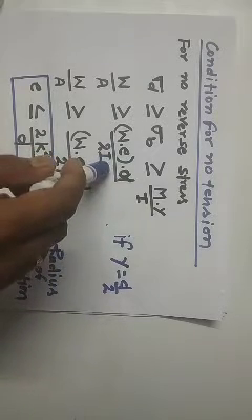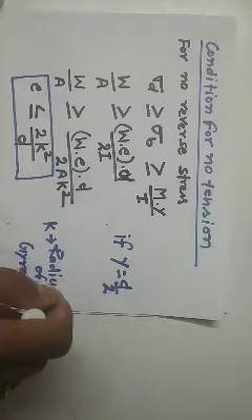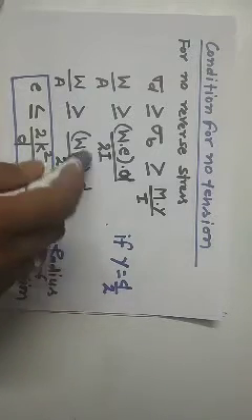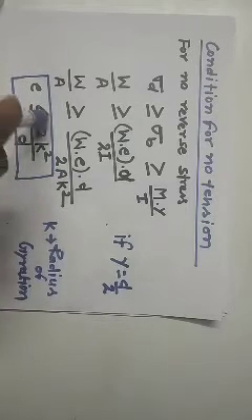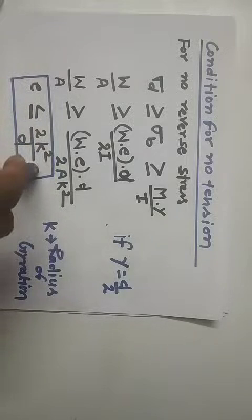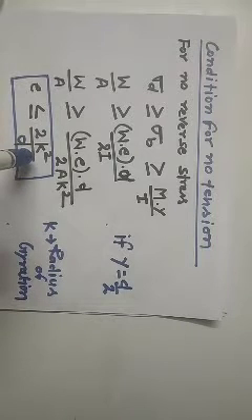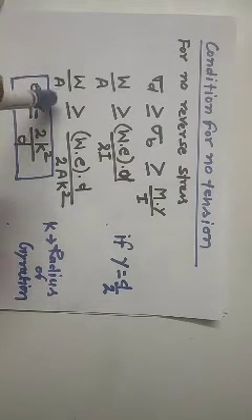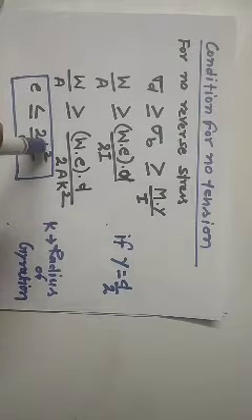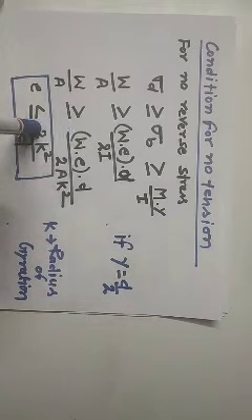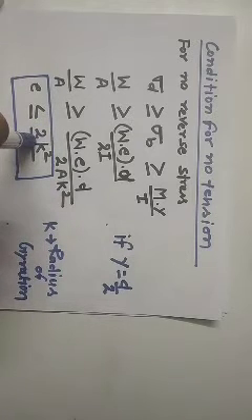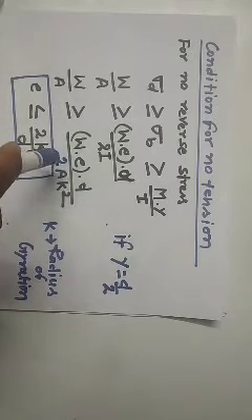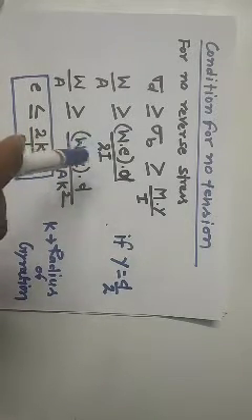Then put I equal to A K square, in terms of radius of gyration. So the expression is now E is less than or equal to 2K square by D. This value says that when we apply load W at distance E, then this E must be less than or equal to 2K square by D. If we apply load beyond this value, there will be chances of tensile stresses in the section.